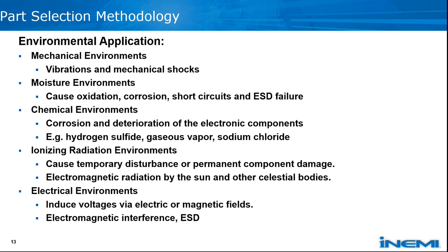We know that depending on the electrical currents, we can see modifications in our components and in the buildup of intermetallics, for example. The chemical interactions that the components are exposed to, and possibly even potential radiation effects can induce these failures. And those are all considerations as we move forward.